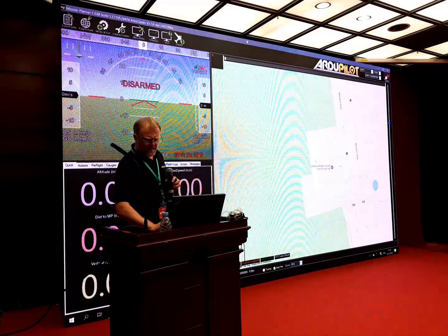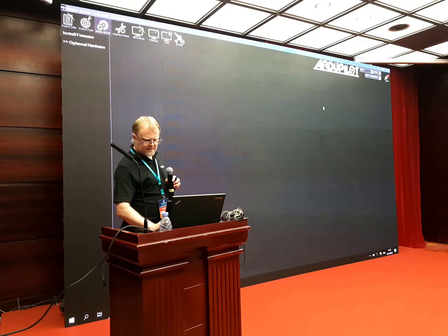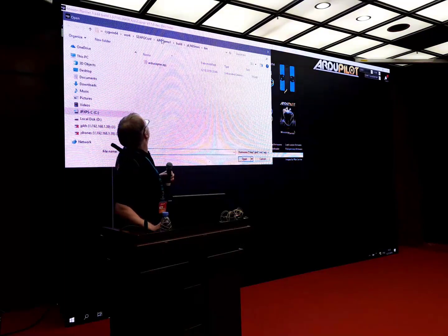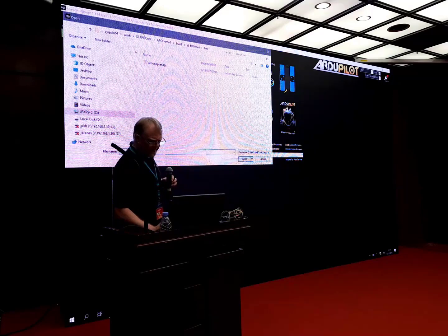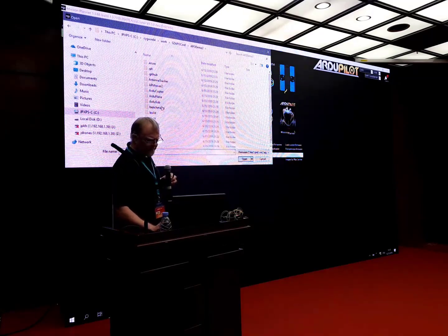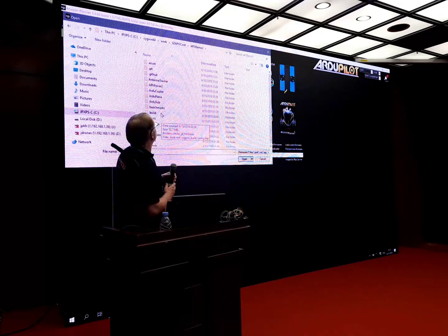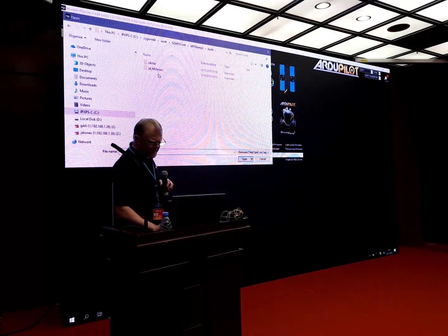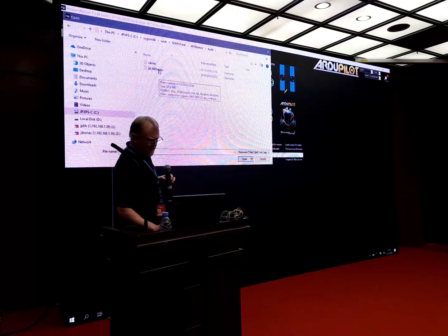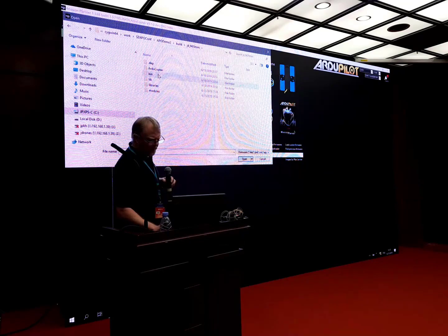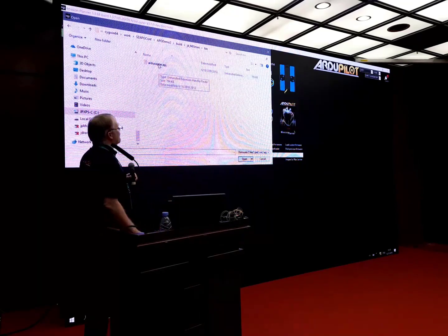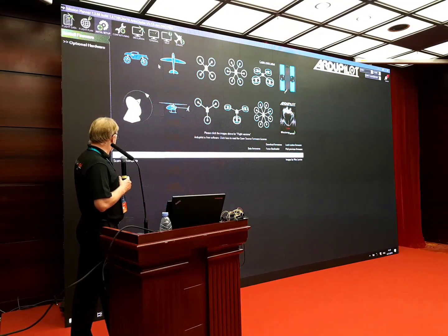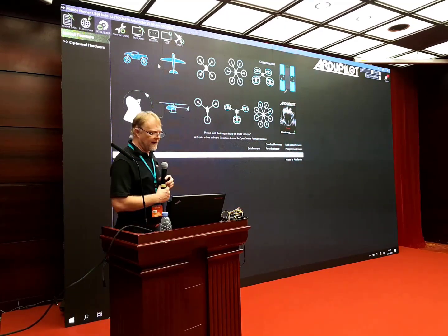Now, let's just upload it: Firmware, Load custom firmware. We were earlier in demo 1, so let's go to demo 2, and like I said, we have the build folder in here. Normally this would be ArduPilot, but I just renamed it to AP demo 2. So there's my board, JDF05 Mini, ArduCopter, and there's the bin folder, and there we have the ArduCopter APJ, which is our binary. Let's hope that it works. Reading hex file, scanning COM ports, erasing. Now it's erasing the flight controller, well, the MCU.